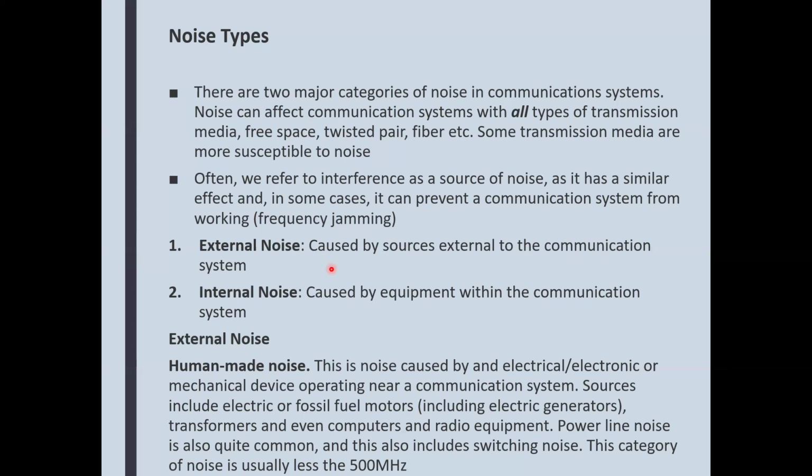So you try to keep data cables at least 1 foot away from any of those, or industrial machinery that employs motors and actuators and whatnot, that can also cause interference within the data line. So that would be the external sources of the noise.